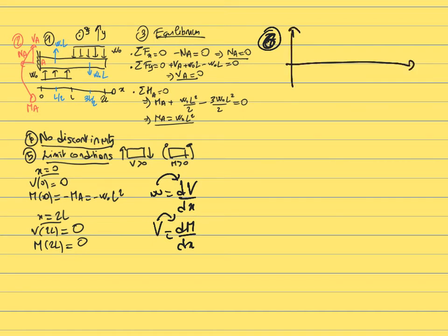The first thing is going to be to plot the load diagram. So in this case, we are going to plot the distributed load as a function of x, and we are going to plot it as a function of the position within the beam. So the beam goes between 0 to 2L, and the distributed load is going to change at x equal L. Be sure you remember the positive convention that we are using in this class. In this case, the positive convention is that the distributed load is positive if it's going upwards.